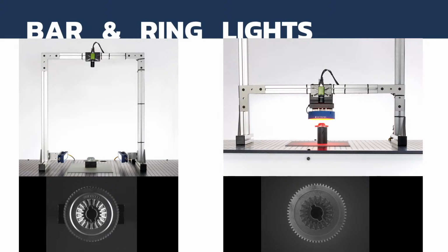So look what happens. I can create dark field imaging with a pair of linear lights, but because my surface is specular and those splines want to capture the directional light, I start getting a dark field image from the linear lights at the right angle, but I can see the reflection from that angle. So when you look at the image, you can almost see four quadrants. There's two dark field quadrants where the lights are coming from the sides, and at 6 and 12 o'clock, it's actually a bright field image because you're not getting light at the right angle at that tangent, and you're just getting scattered light in there, and you're losing the dark field effect in between.